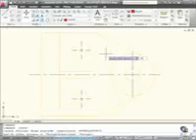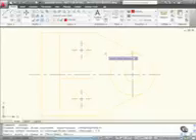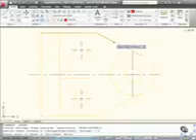Like so. Now the distance is inconsequential. It's purely a generic distance. It doesn't have to be millimeters or inches or anything at the moment, because all we're demonstrating is how an object is offset through that distance. So when I press enter now, it'll ask me to select the object to offset. So I'm going to select this polyline just here, and then I'm going to move inwards inside the shape and left click again for the direction of the offset.